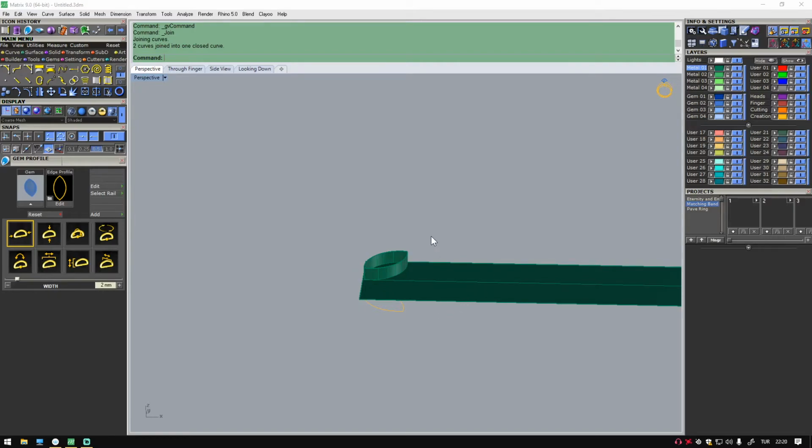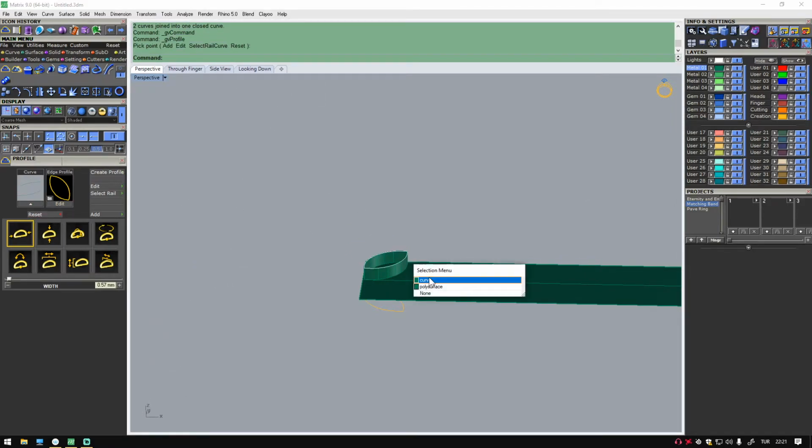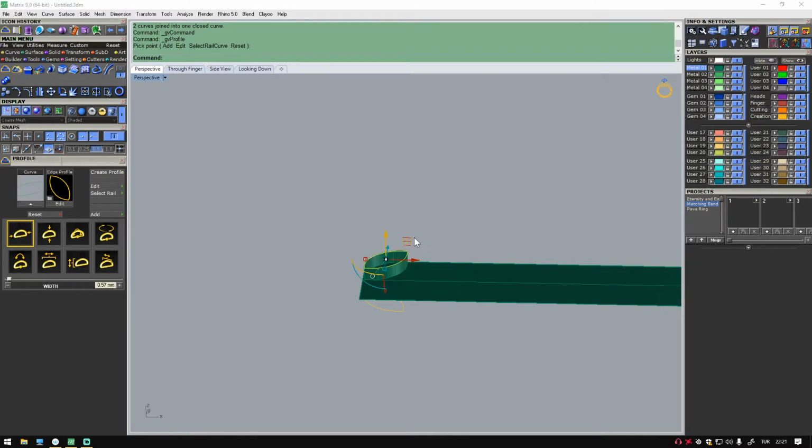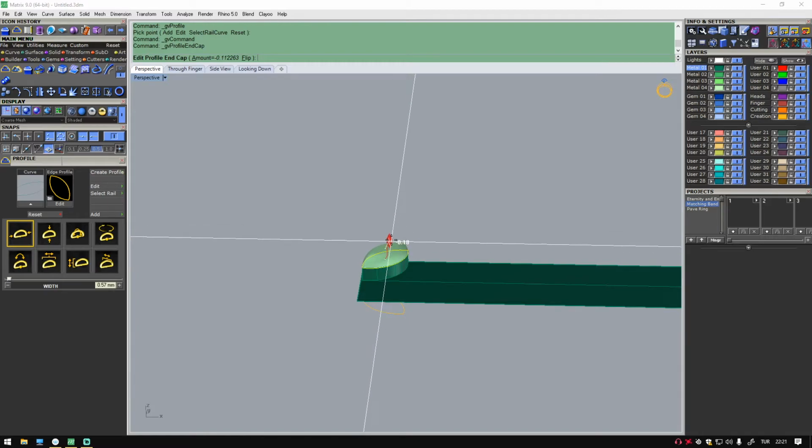Now this is a curve that we duplicated or designed. I want to turn this into a profile. And if you go to tools, and if you go to second page, there is this profile command. If you click it once and the command pops here, you need to put your curve inside this box and just right click. Now it turned this curve into a profile. Now we can go and click this profile and cap. And as you can see, now it's a dome that you can go higher, you can go lower. I'll go with something like this, right click.